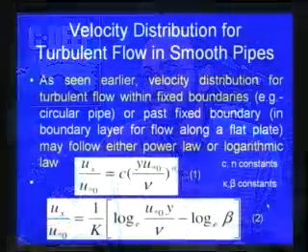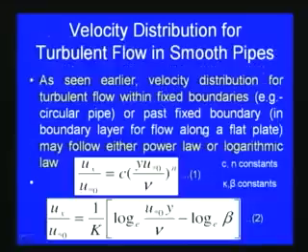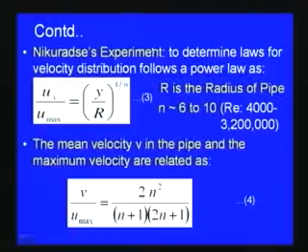What we have seen earlier with respect to flow over a flat plate, we are now trying to apply in a very similar way to pipe flow by using the same concepts. Using the power law there is one equation, and using the logarithmic law there is another equation. Also, Nikuradse has conducted a large number of experiments as far as turbulent flow in pipes is concerned, and he has also derived certain expressions for velocity distribution in pipes.